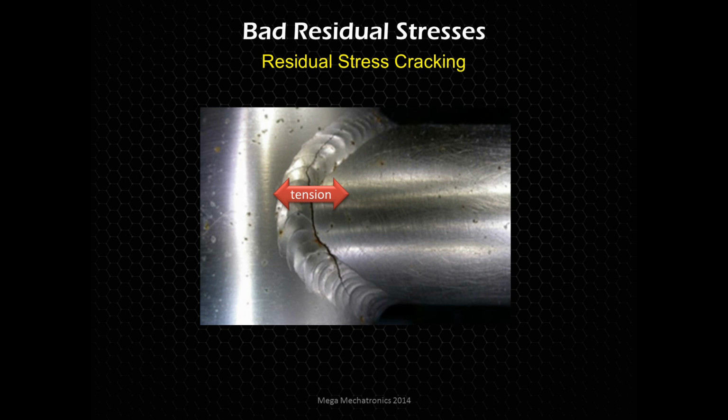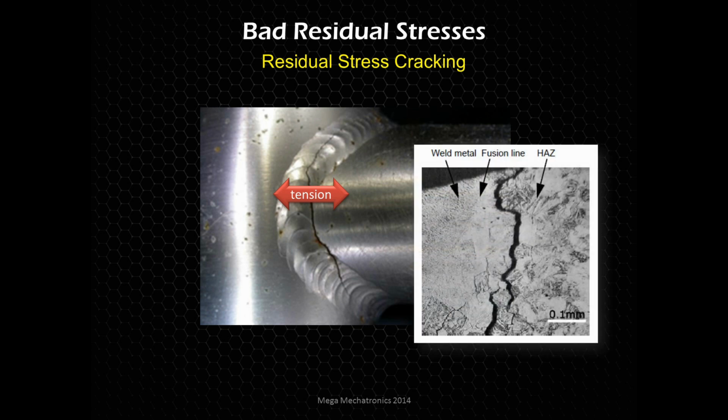So having that residual stress in there, you can imagine a tiny corrosion pit gets generated right at that fusion line, and then it just gets worse from there and cracks. A part that was properly manufactured could be filled with corrosion, and because it doesn't have these residual stresses in there, could maintain its structure.